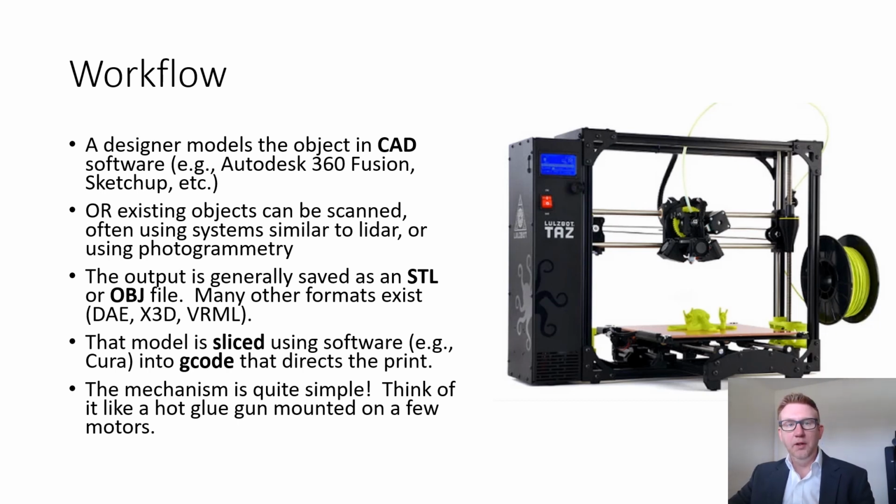The level of detail that you print essentially correlates to print time. So the more detailed you want to be, the longer it's going to take. You can produce very thin layers. We'll do anything as small as a 1/10 of a millimeter. So 10 layers is 1 millimeter, so quite fine. All the way up to about a quarter, or sometimes even 0.38 millimeters per layer. So each layer is pretty small, and the smaller you make it, the more precise the model looks.